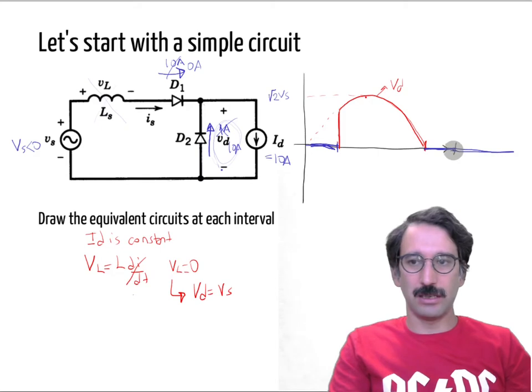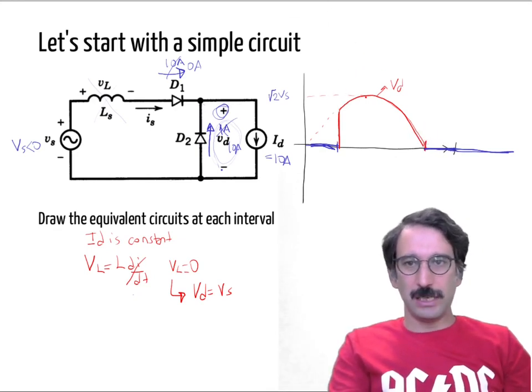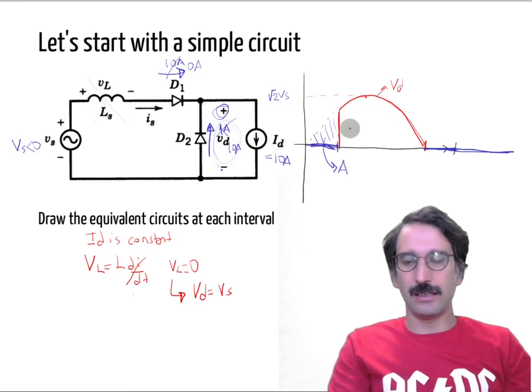I will keep 0 voltage. I will not have negative voltage at the output, because whenever I want to get negative voltage, that diode will get into conduction and make it 0. So the main thing you need to remember, let me call that area A: without any line inductance, if we had an ideal grid, I would have that average voltage, but due to commutation I lost that blue area, so my output voltage average is now reduced.